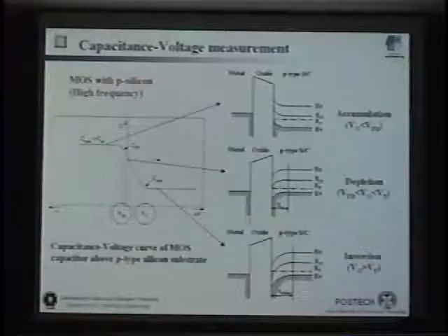Well, if you measure capacitance with a sweeping voltage, basically you get this kind of graph when you use a P-type silicon wafer and then SiO2. This is a well-defined CV plot. In this region, holes are accumulated at the interface because this is P-type silicon. Then you get the maximum capacitance based on this oxide dielectric layer. And this one gives you the dielectric constant of the insulator. And if you sweep the voltage, then you get the so-called flat band voltage, and then threshold voltage.